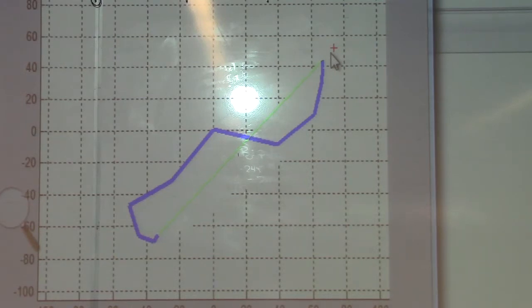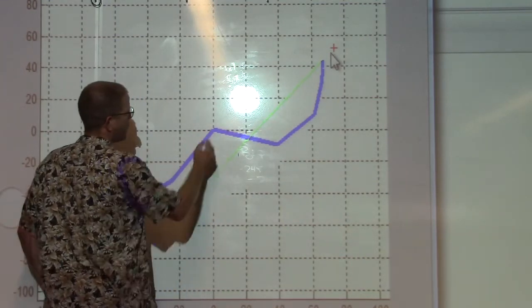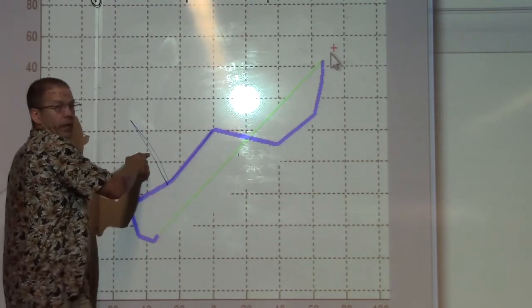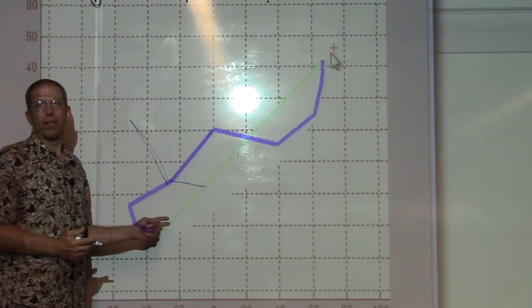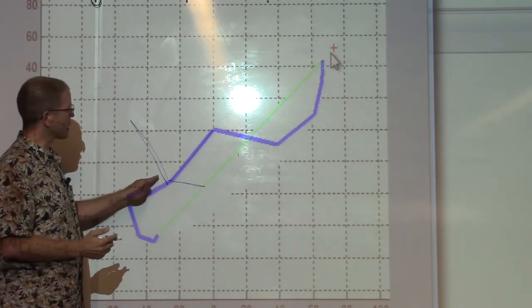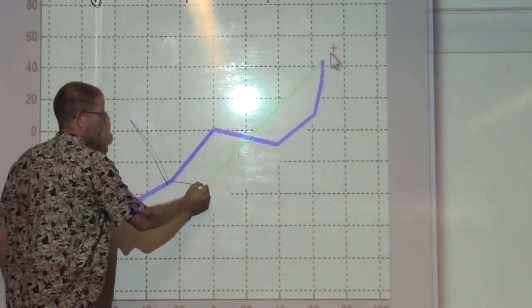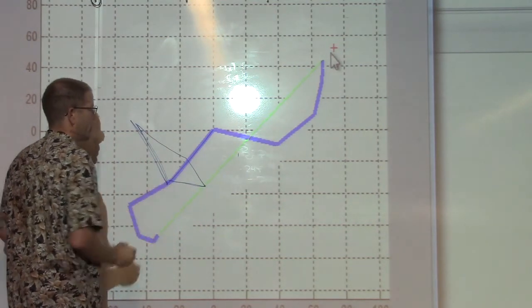Okay, what happens on occasion, particularly when you have a joint that crosses over another joint, so let me sketch it here while this thing is sitting here thinking about the meaning of life and stuff, is let's say that we've got a situation where we have the second and third segments right on top of each other. So it might look something like that. What you'll see as it's moving through is a sudden erratic behavior. So it might do something like that.